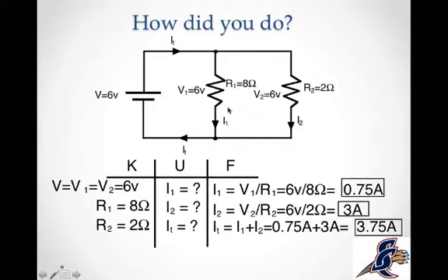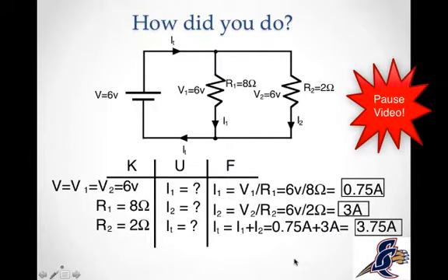It's kind of like opening up a lane on a freeway, and so we'll talk about that next, how we're going to get more and more current. If you see here, when you add resistors in parallel, it's kind of opposite what you do in a series circuit. When we added resistors in series, the resistance got greater and greater. But when we add resistors in parallel, the total resistance is getting smaller and the total current is getting greater. More on that next.